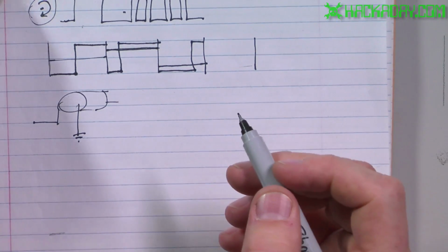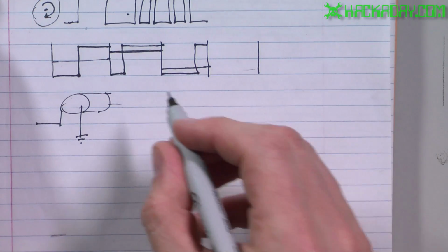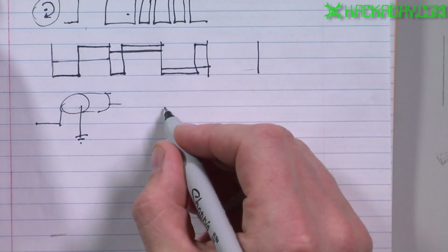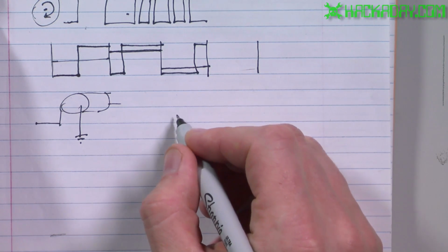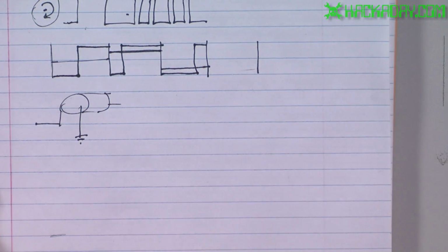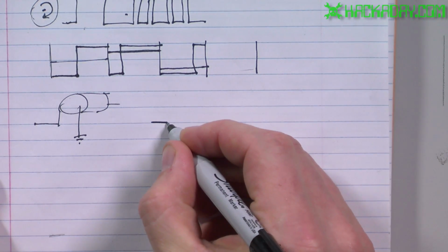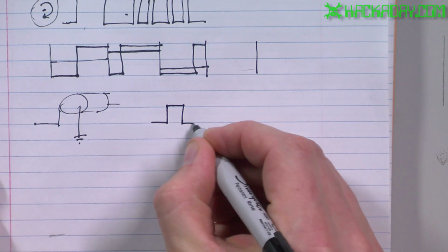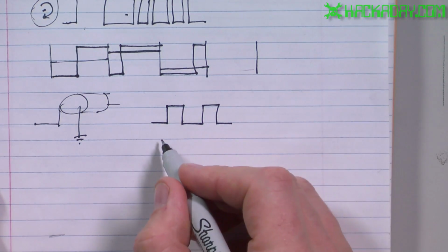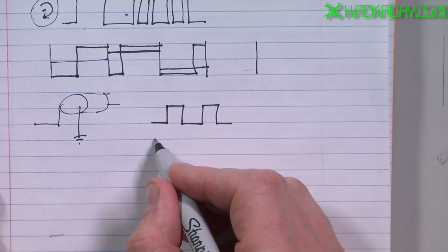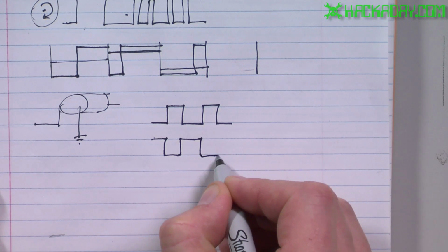The way that I'm going to show today is called locked antiphase. And what this is, you have 2 pulse width modulation signals, or it could be just one, and you use some sort of logic to invert it. So if we're doing 2, which is what I'm actually doing on the 3Pi robot, the signals are going to look like this. They'll be completely opposite of each other.